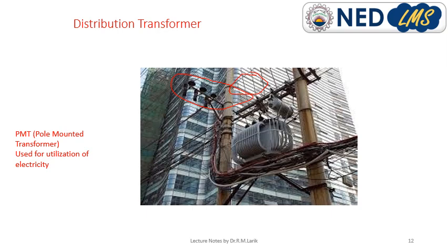I visited almost every corner of Karachi due to that project. I was an assistant executive engineer at that time in K Electric. We installed check meters for the purpose of theft detection, to see how many units are generated and how much is billed from that transformer.